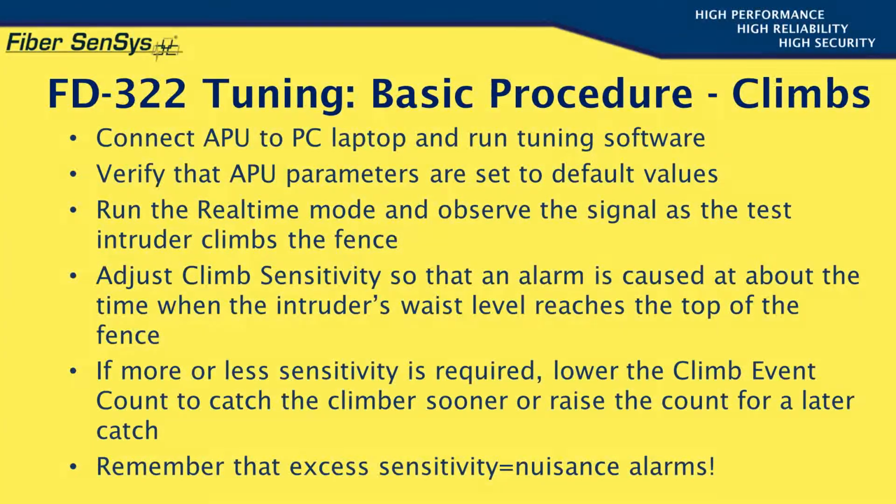However, avoid low event counts, that is, 2 or less, since nuisance alarm sources such as a branch blowing in the wind or an animal brushing up against the fence may create unwanted alarms. Excessive sensitivity can equate to nuisance alarms, so interactively adjust sensitivity and event count for the best compromise.